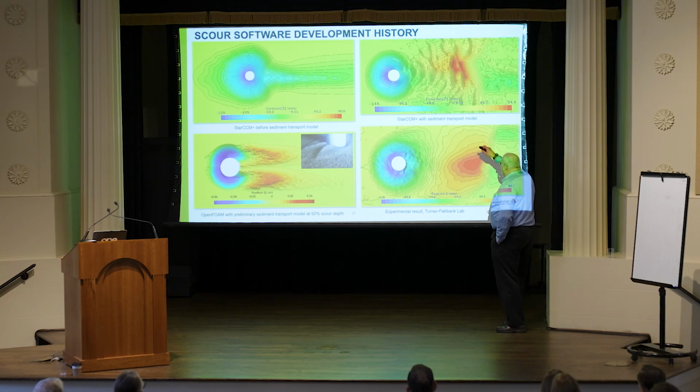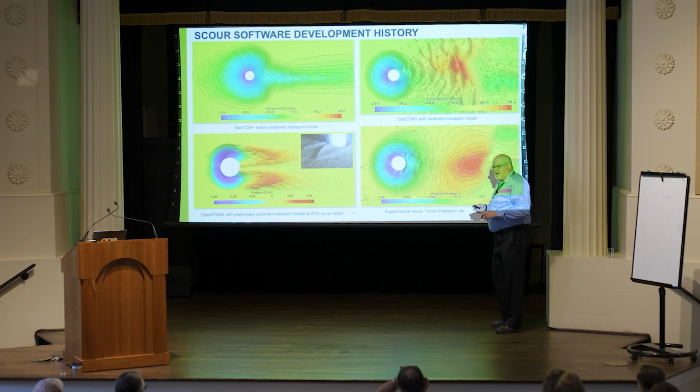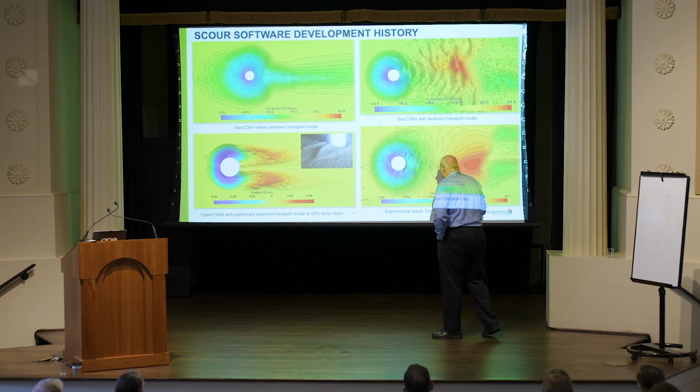And he ran this case to the very end, and what you see is more of a development of large dunes. You can see that in some of the other videos later. That is a discretization problem, right? Because much of the sand moves in form of dunes, which means lots and lots of little changes to the riverbed in areas that are not terribly interesting, right?